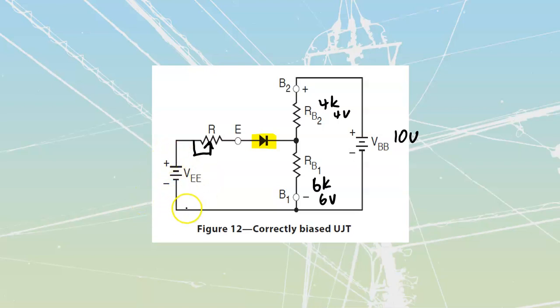This voltage that we have over here, as long as this voltage exceeds 6 plus another 0.7 that I'm going to have across there, I'm going to be able to drive this thing into conduction. And I would be able to, at that point, use this as a switch to drive current out and through this section over here. Here's how we go and change these values of voltages.